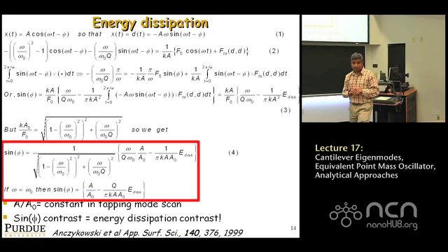So that entire term in the integral is actually the net work done due to dissipative forces, or it's the energy lost due to dissipative forces in one cycle of operation. Because if the interaction forces are purely conservative, that integral must be zero. Because in one cycle of operation, it has to be zero.